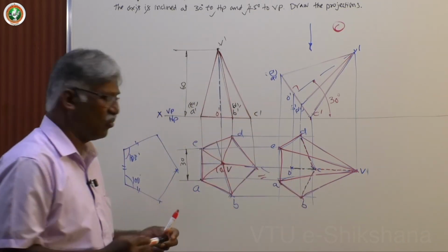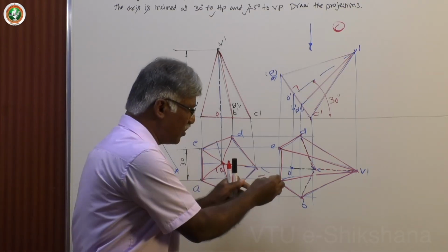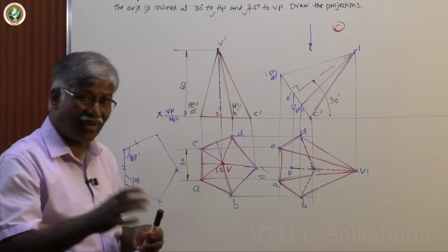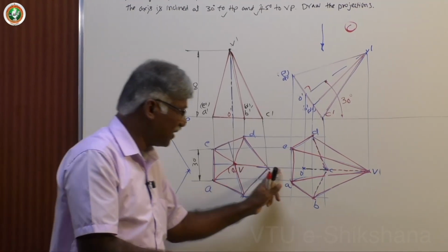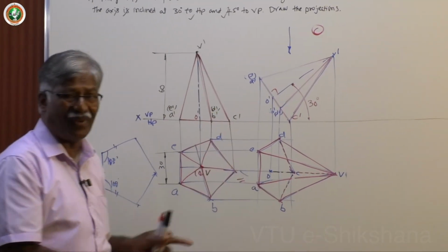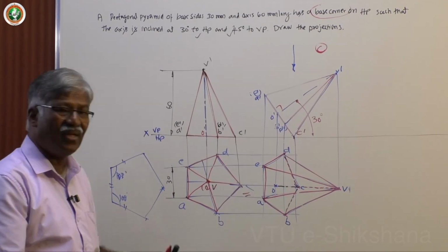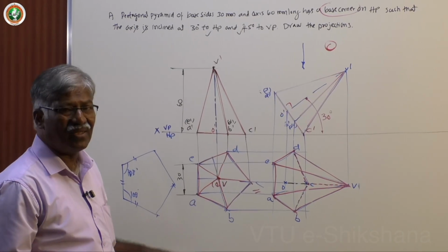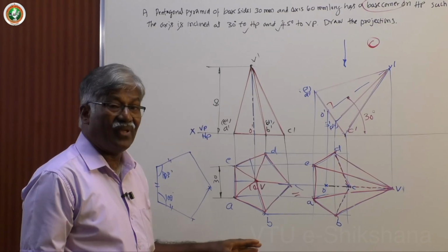Okay, you can use 0.25, 0.35 in the computer, and what best you can do is zoom that area and then remove whatever line is available, then replace or modify that. Suppose a continuity line is there, then you have to go for split, otherwise you use trim, then you keep these 2 out, then you can replace that with the axis. So, this is how we can complete the top view, second figure top view of the problem.